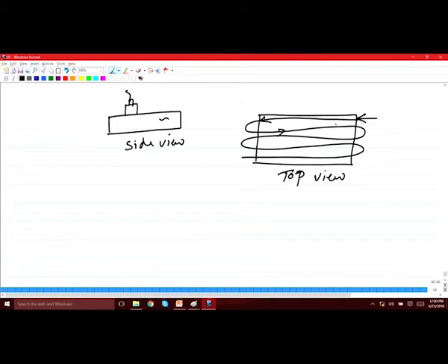Like this. And so on. Okay. So, if this defect, if you see the 2D view, it may be something like this. Okay. And now, since you have collected the echoes as a function of each of these reflecting points, you will see a 2D type of view in the display when it is finally displayed on the system. Okay. So, this is the C scan view, this is how it will look like.